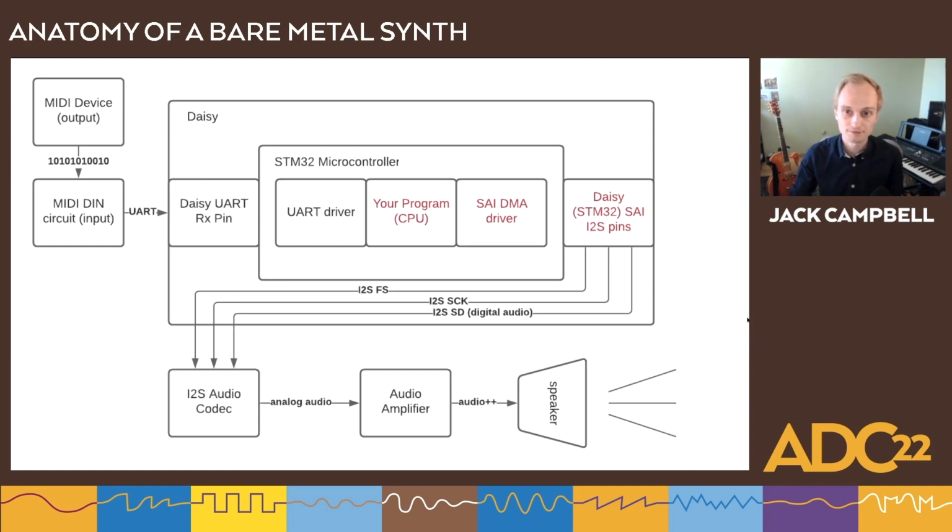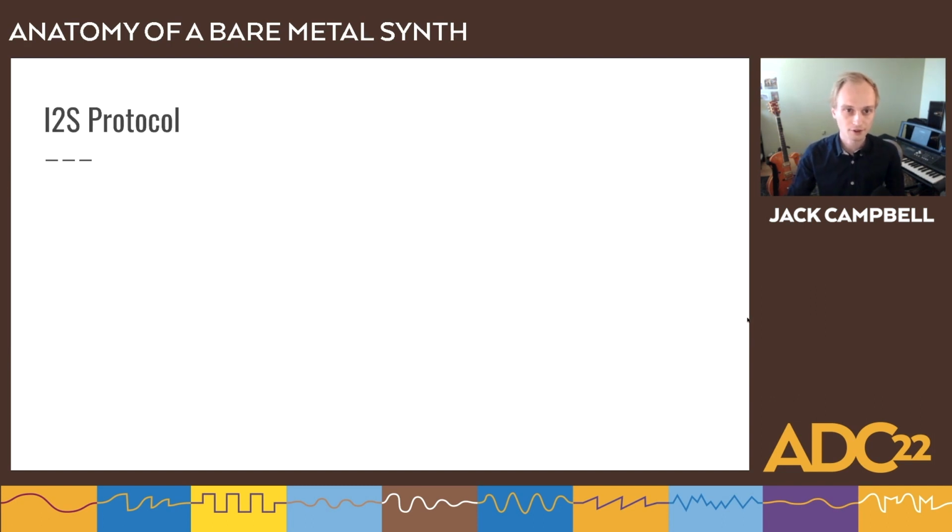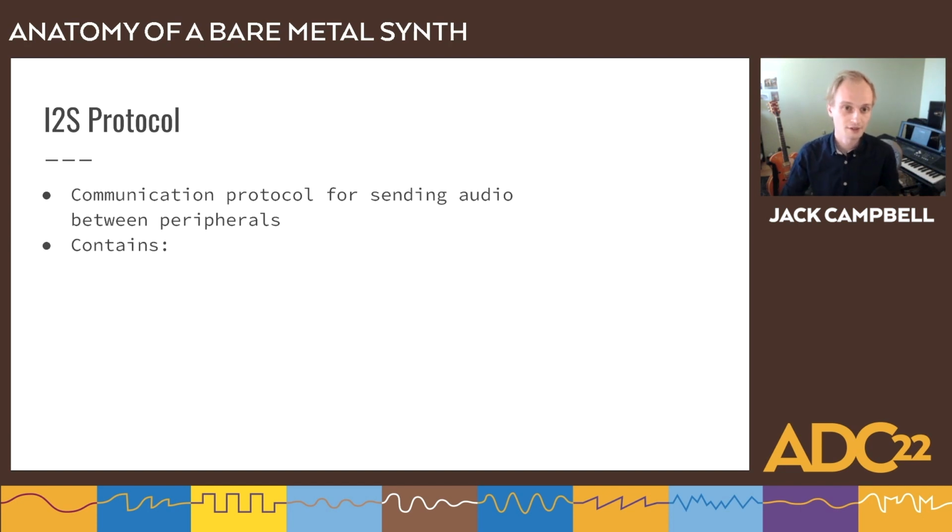What I want to focus on is how these floats that we've returned to the audio hardware actually become real sound. That's where the SAI, or serial audio interface, comes in. But even before we get to the serial audio interface, I want to talk about what it is generating. We know it's receiving audio, but that audio is in the form of another serial communication protocol called I2S, which has audio data in the form of integers, not floats, which is important.